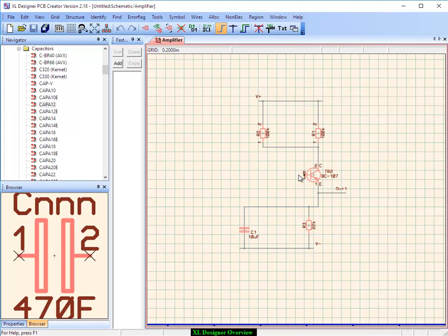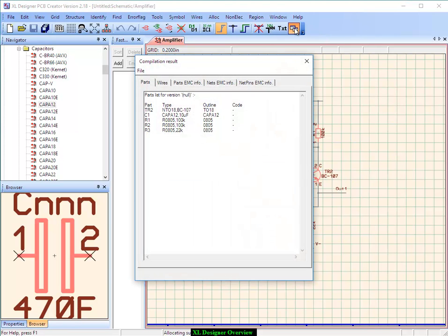So there is a little circuit diagram, and the last thing we need to do in order to create the parts and wiring list is extract the parts and net list from it. So we've got an icon, a shortcut icon, extract parts and nets, and then this is the list of parts from this little circuit diagram. Gives you the part reference numbers, the values and the type of components, and what footprints are called up.